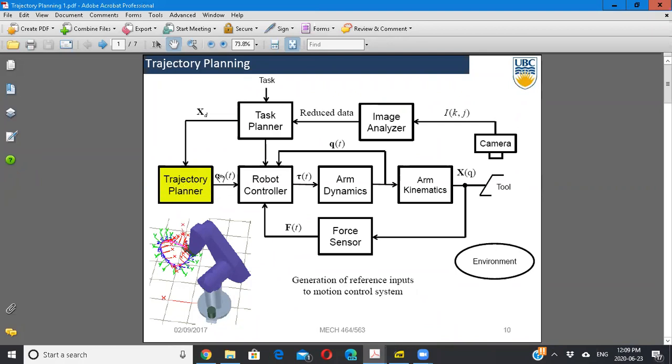So what happens is you might not tell each joint to go to a certain position. All you know is, well, I want the end effector to go from this position to that position. In other words, I have Cartesian motion, a Cartesian position and Cartesian orientation. In other words, I have the position and orientation of the end effector frame. That's easier for me to know where the robot is and where I should take it, instead of computing the inverse kinematics part, just like coming up with these joints by myself.